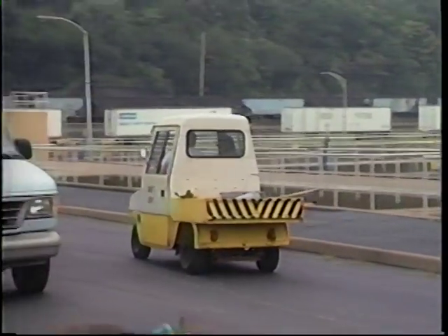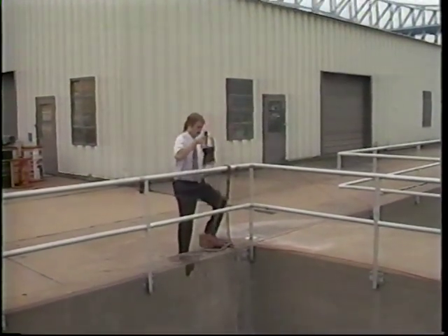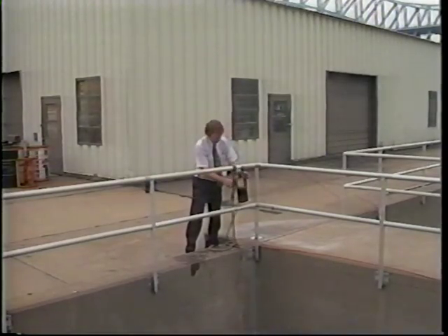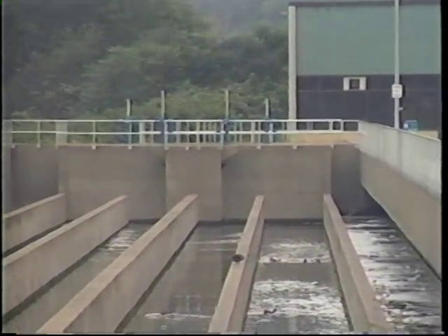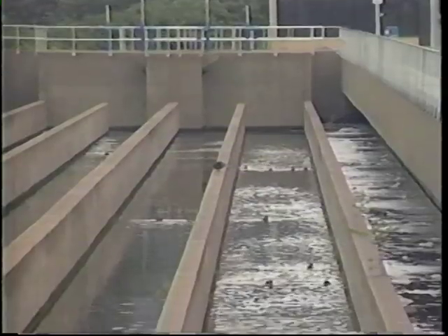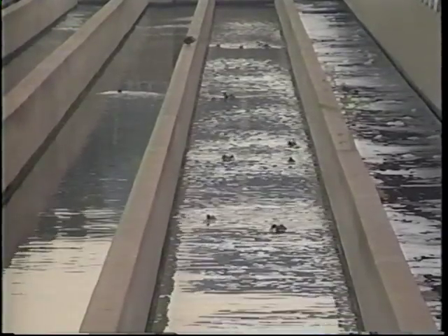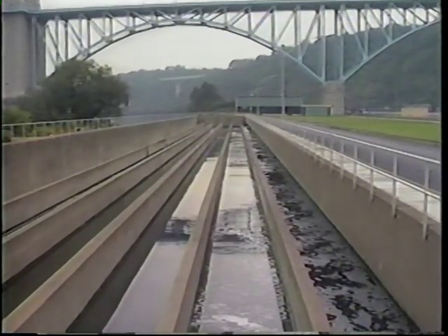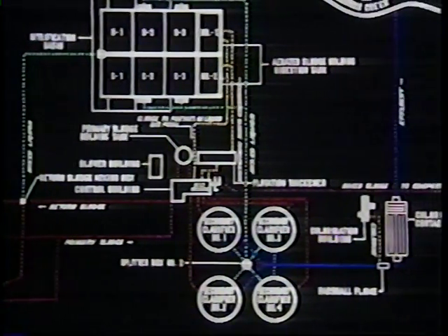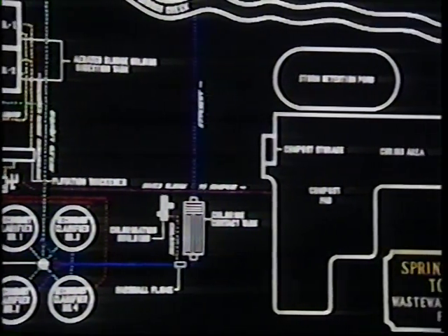Skilled wastewater treatment plant operators are essential for the wastewater to be treated properly before and during the final stage in the treatment process. Usually, the final destination of wastewater within the treatment plant is a process known as disinfection. In the disinfection stage of treatment, it is the treatment plant operator's job to assure effective kill of harmful disease-causing microorganisms known as pathogens. While many microorganisms die off during earlier stages in the treatment process, sufficient quantities of pathogenic organisms may remain and cause health hazards to humans and animals. Therefore, we have this important